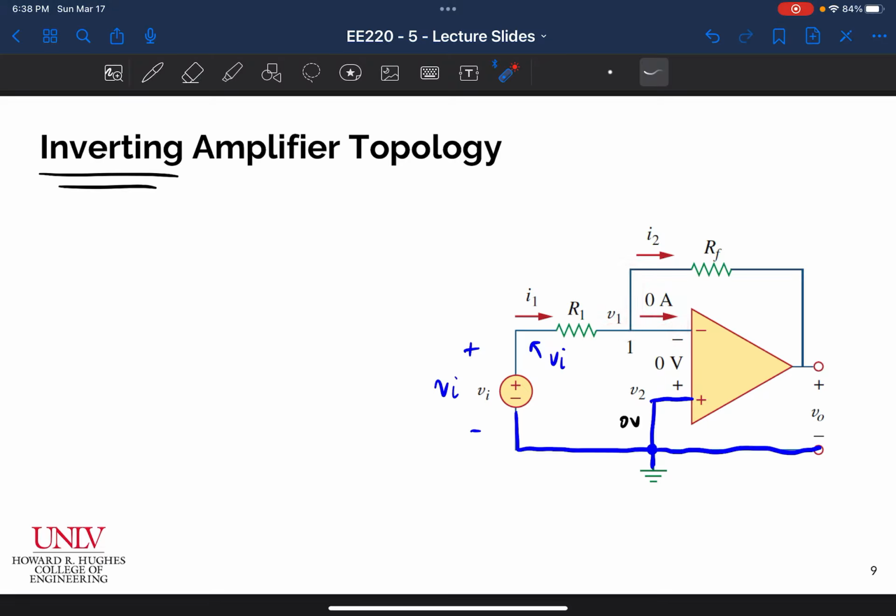Well, if I remember my op-amp rules, my golden rules, it tells me that the plus terminal and the minus terminal have to be at the same potential. If I know my plus terminal is at 0 volts, then my minus terminal ought to be at 0 volts also. This is exactly what the figure already shows, no voltage drop across these terminals. And it even highlights the other golden rule for us, and that is that no current can flow into the op-amp input. So it's showing me a current I1 flowing through this resistor R1,